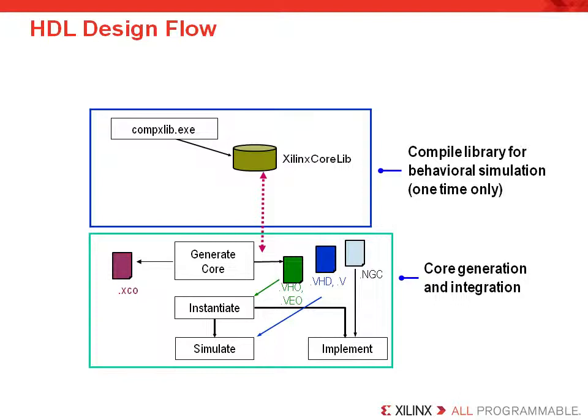CodeGen will produce an .xco file, which is a component's options log used to create the core. This file is automatically associated with the ISE software and is frequently used to regenerate the core. Finally, the most important file made is the .ngc file. This is the core netlist that you will need to integrate the core into your design.